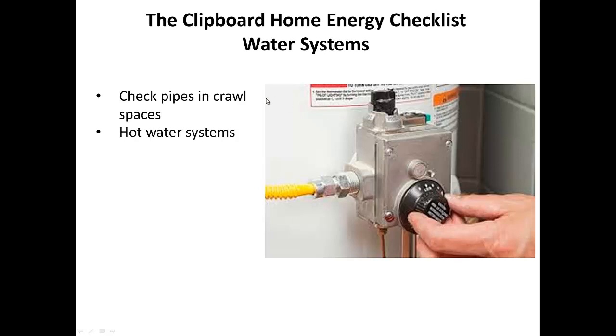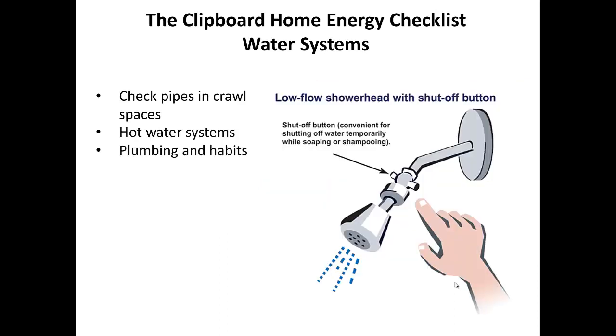There are insulation kits that you can put on the outside, but you want to be careful with those insulation kits because if it's a gas hot water heater, you want to enable that gas to still be able to breathe, to still get air. So at the bottom down here where you light the pilot light, etc., you want to make sure that you've installed that correctly. And there are plenty of websites that show you how to do that.